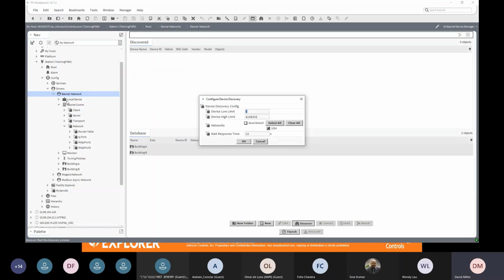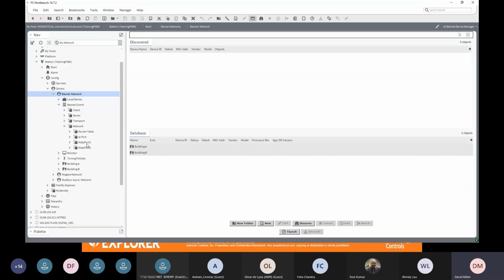When I'm finished, I can go to my platform and do a station copy, where I copy this configuration into an FX80, at which point it'll start running inside the FX80. At that point, this MSTP port 1 would start functioning because it would have a valid COM1 that it can connect to. And likewise for port 2, it would connect to COM2.